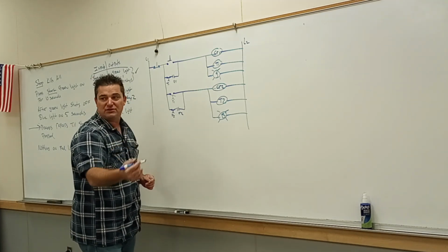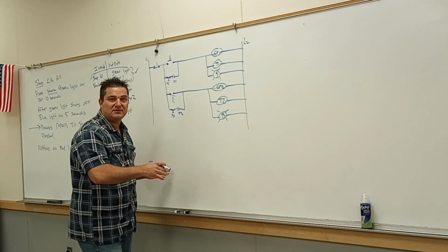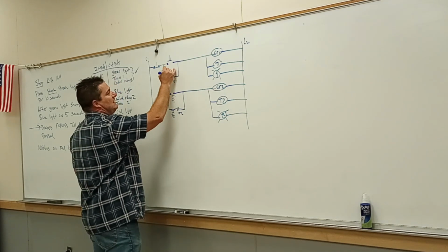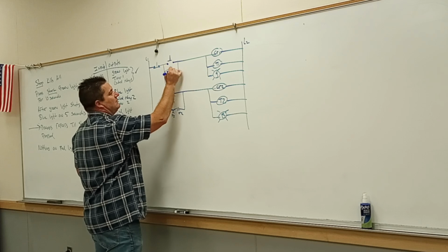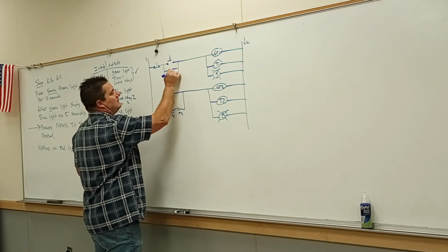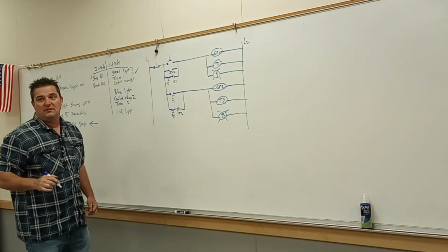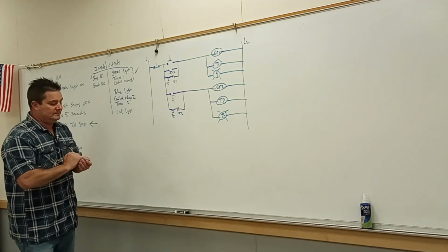So then because it's a start, stops are in series, starts are in parallel. You notice I left a little bit of a gap right here. That's going to be timer 2. So now,